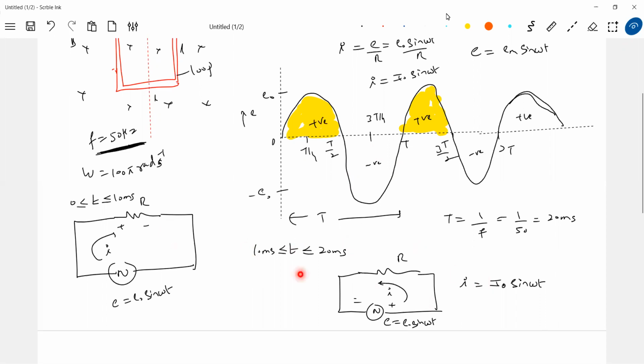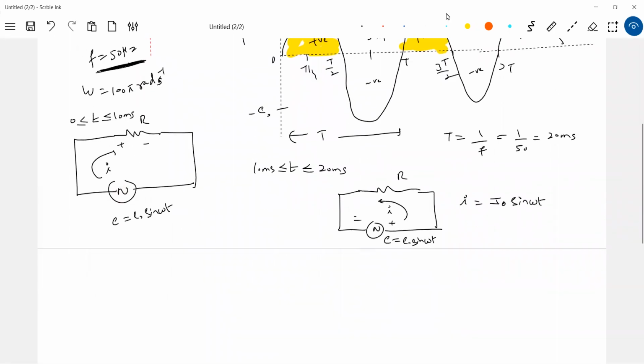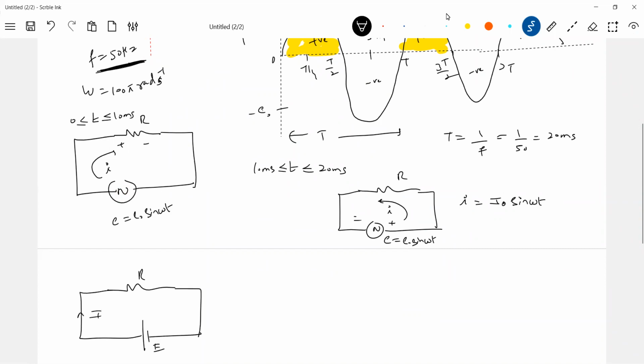In short, we'll call it AC, and we show it by a symbol like this here. Alternating, and next we'll compare with a direct current signal. What do you mean by a direct current signal? If you take a source, there's an EMF E, there's a resistor. At all instants, the current will be constant here, no? I'll call it I DC.